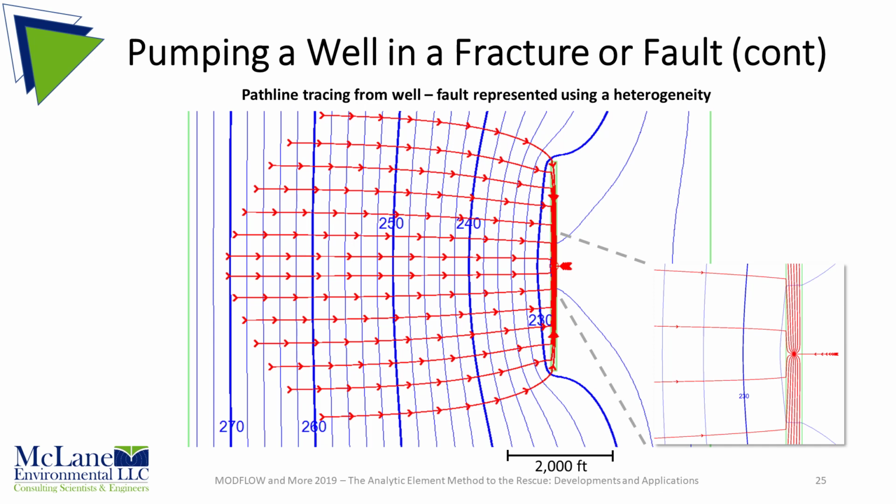That is easily taken care of if we change the fault zone in the model from a line element to a long, narrow zone of high hydraulic conductivity, representing the transmissive flow zone created by the fault. Here the pathline pattern shows groundwater west of the well and fault entering the fault zone, forming a broad capture zone, and then flowing along the fault to the well.